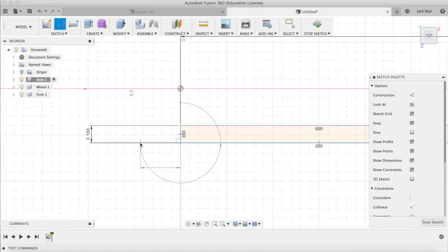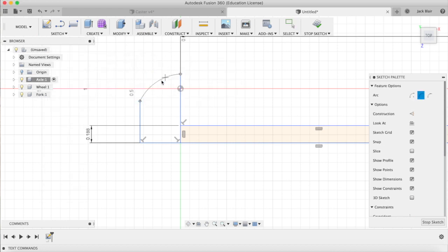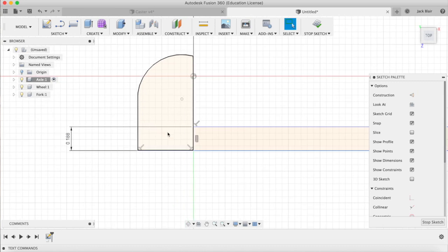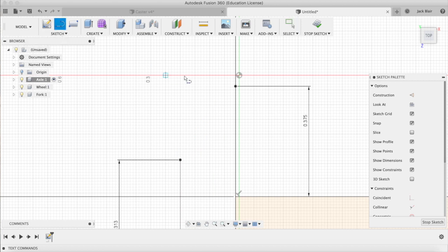So let's create a line here to there, from that point to this point, from there up, and an arc. None of these points are correct right now. This is just the general shape that we're going to be using. Then we can go in and put the dimensions in later. You can see here I forgot to put it in, so I'll just draw a line like this. I'm holding down D to parameterize it. I can just paste in my value like that.